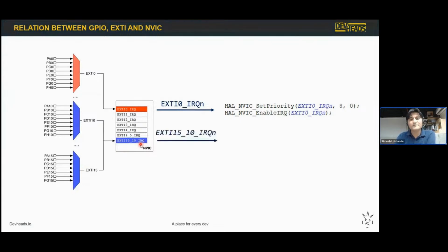So as soon as this external interrupt 13, EXTI13, gets fired, we have to write these 2 lines of code, because by writing this NVIC enable, we are enabling EXTI13. I'm saying 13, but it's written 15 down to 10, but it's the same thing, because external interrupt 13 belongs to the same vector, EXTI15 down to 10. And to set the priority for the second switch, which is connected to the PC13 pin, I'm going to set the priority 7.